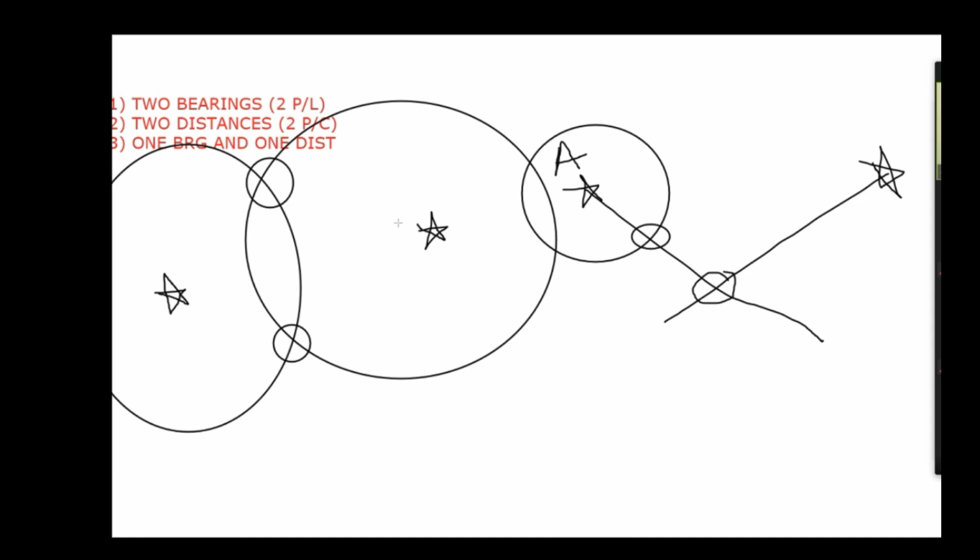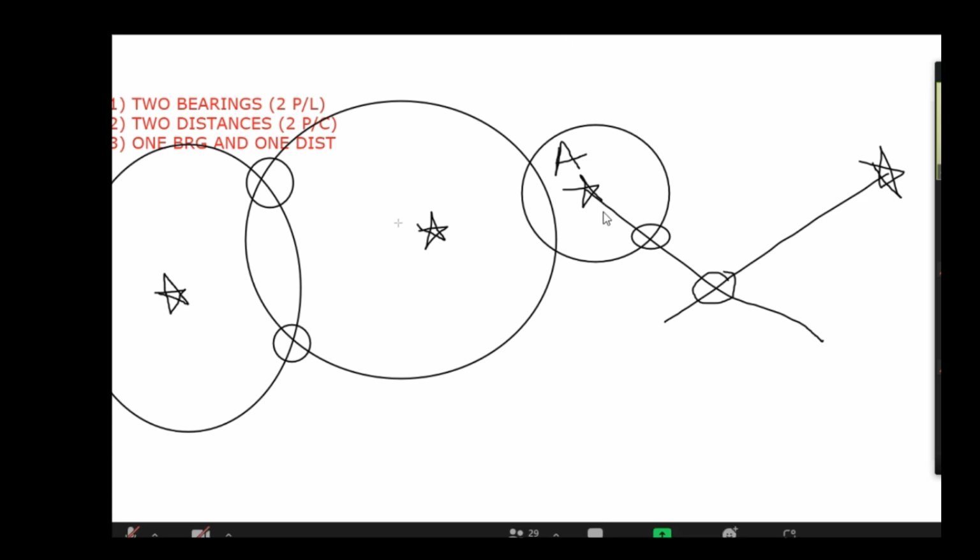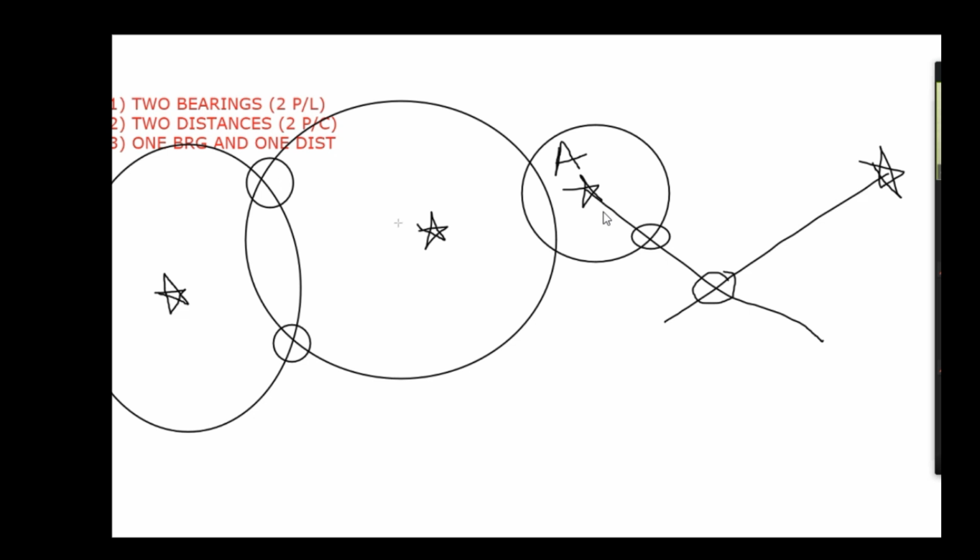In case we get two distances at two different times, again at 10 o'clock from one lighthouse you have a distance of 8 miles. After 2 hours, maybe at 12 o'clock, you get another distance from another lighthouse, maybe 5 miles off. Then the first circle will be transferred. So ultimately, after transferring, we get the two pieces of information. It is always a requirement that to get a position, two pieces of information are required at the same time. If it's a different time, then you have to transfer one piece of information and superimpose it on the second. So this is the system.